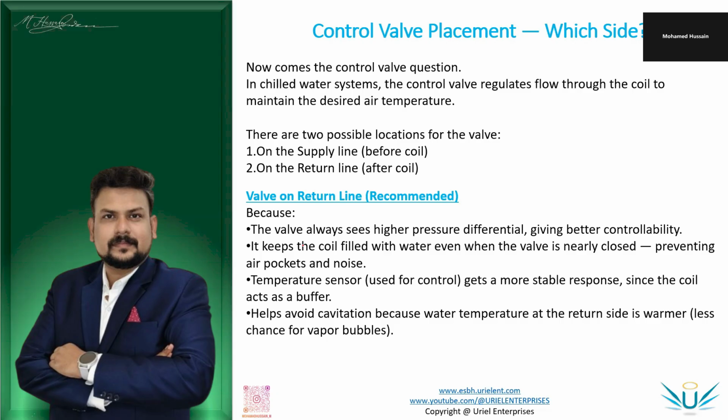So the major recommendation is that the water has to fill the cooling coil, and the valve has to be placed in the return line. Again, some mechanical contractors recommend placing it in the supply line, but those things have to be confirmed in the MEP drawing, the mechanical, electrical, plumbing drawing. We will show a realistic example after this slide, while sizing the AHU cooling coil valve. Okay, so next slide.